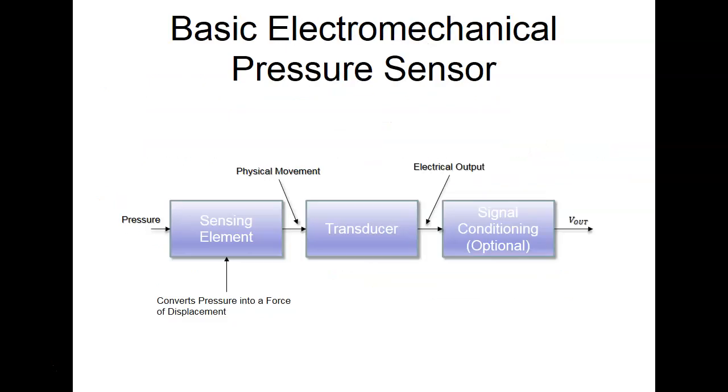So this is basically the makeup, and this is almost true on all sensors. Even though we have thermistors, a thermistor changes its resistance with temperature. But the problem is we cannot process resistance. We have to process either voltage or current. So we have to have some other transducer that converts resistance into voltage. For most sensors, it's pretty simple. We just add a fixed resistor. Or if we want to set a zero reference, then we put it inside what we call a Wheatstone bridge, right? Okay.